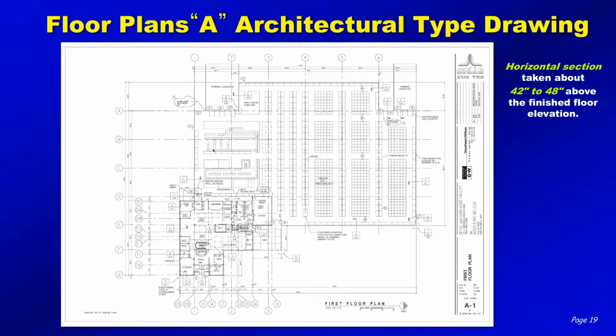And then the floor plans, which is the beginning of the architectural. Almost all jobs will start off with, although it may have some general notes, but it typically will start with the floor plans, starting at the lowest level and work its way up through the building. And the floor plans are nothing more than looking at that building as if you were standing up about waist height and you just cut a big section and you're looking straight down on top of it.